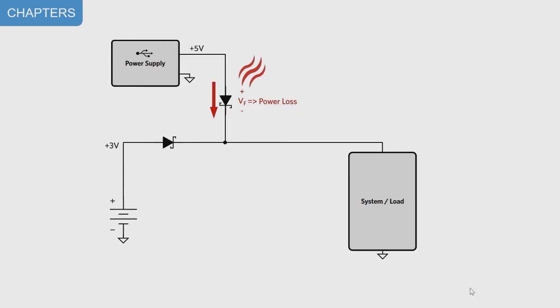Second, when a Schottky diode is reverse biased, a leakage current forms. Most non-rechargeable battery manufacturers warn against such unsafe trickle charging. If a Schottky diode is reverse biased and starts to charge a non-rechargeable battery, safety becomes a critical concern.